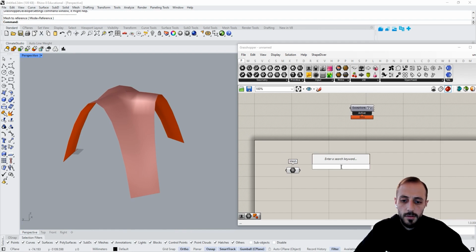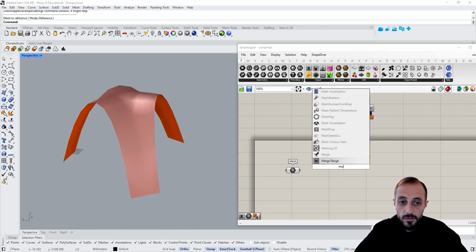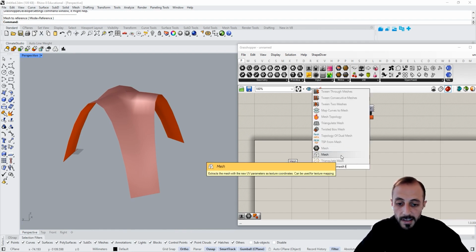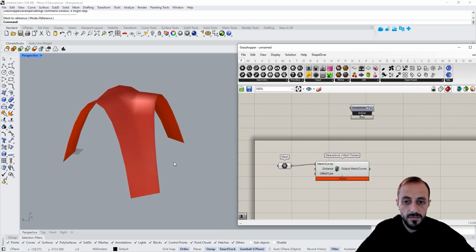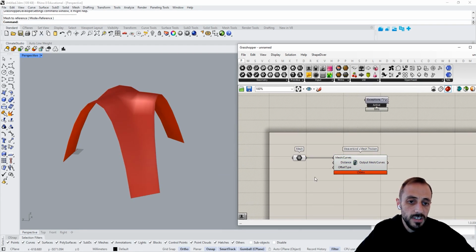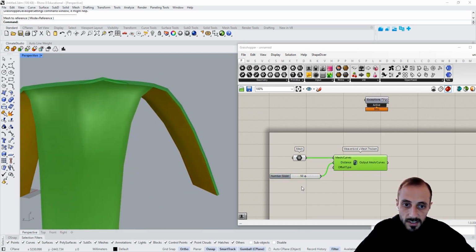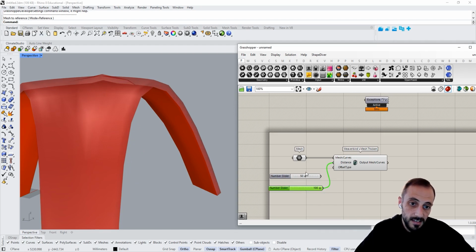The first thing that I'll be doing, I'll be adding a thickness to this mesh, Thicken from Weaverbird. This is a plugin which I already covered, so you may find the resources to this plugin. And as you see, it started to add some thickness to it, right? And what I would be doing as a distance, let's say 5 centimeters. But you see, it's relatively small, so let's put it 10 centimeters. 100 millimeters, 10 centimeters. It's completely up to you.